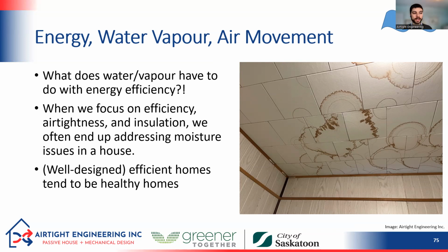When that humidity gets in contact with the ceiling tiles, it creates condensation within the tiles, and then this very alarming looking staining. So if we made this building more efficient by adding additional insulation into the attic, chances are we would solve that moisture problem at the same time.